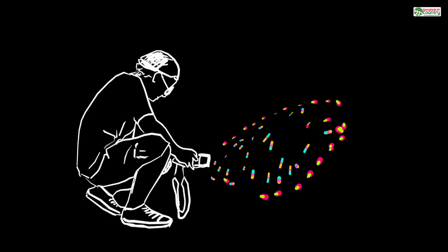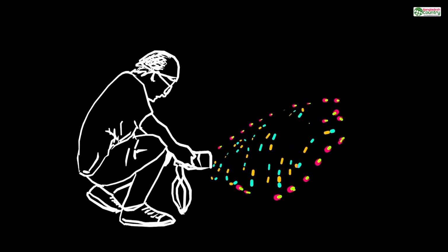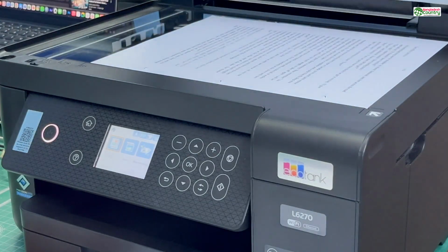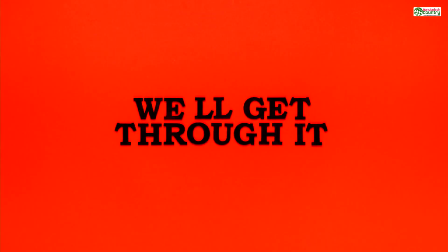Now imagine you designed a wall that's only 0.2 millimeters thick. The printer literally cannot create it. It's like trying to paint a pinstripe with a fire hose. The software will try, but the result will be a pathetic, stringy mess, or more likely nothing at all. The printer will just skip it, leaving a gaping hole in your model.